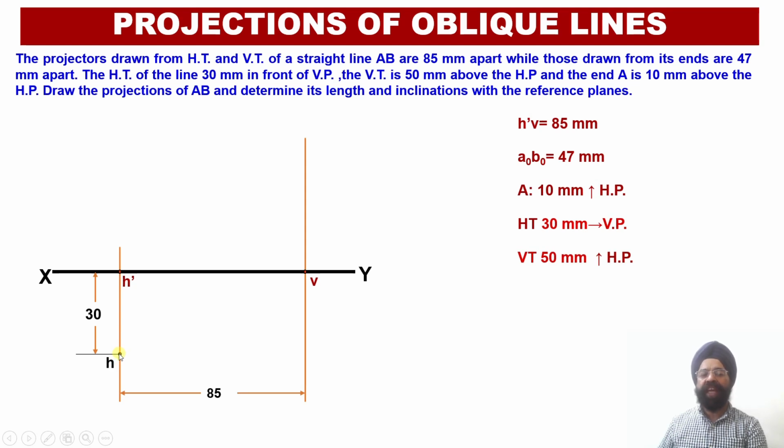So I have been able to obtain one point through which my plan projection line itself, or its extension, is going to pass. Two points I have obtained corresponding to the horizontal trace, since the measurement of the horizontal trace was available with me. Now second, I have been provided with the measurement of the vertical trace of the line. In case of the vertical trace, my plan projection line should be passing from the XY reference line. So this is the second point through which the plan projection line should be passing. The first point I have obtained over here, this is the second point.